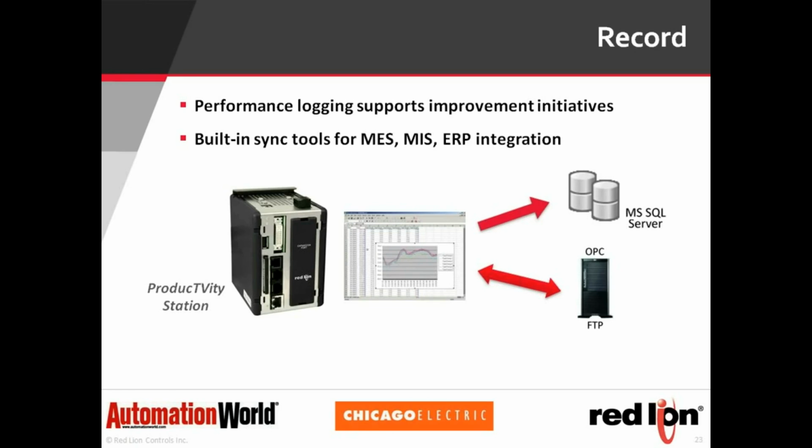You're going to want to log those andon messages. At the end of the month, you're going to want to run a Pareto analysis. Take a look at the reasons you had machine downtime issues. Attack the top 2 or 3 problems that you've had. So make sure that the tool that you select has those logging capabilities, and also make sure, we want to keep the IT people as our friends, that those tools integrate easily with MES, MIS, and ERP systems. Make sure it integrates into the back end.